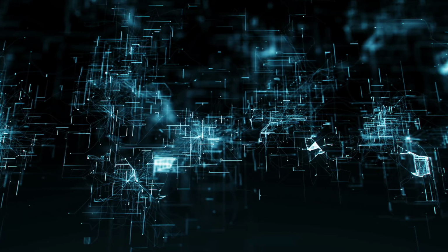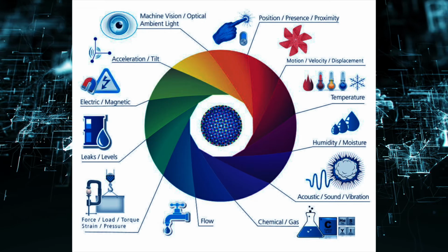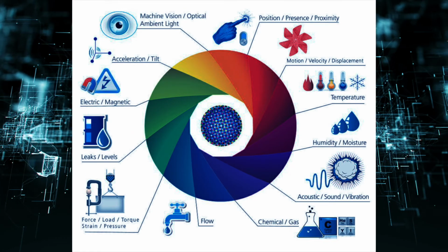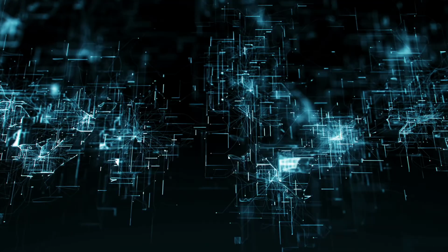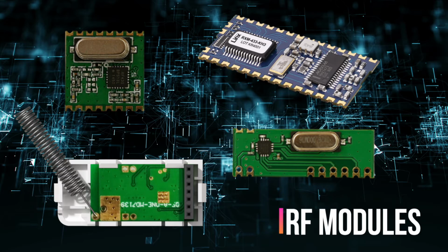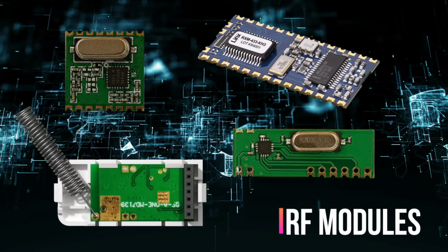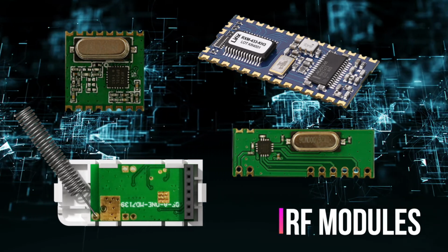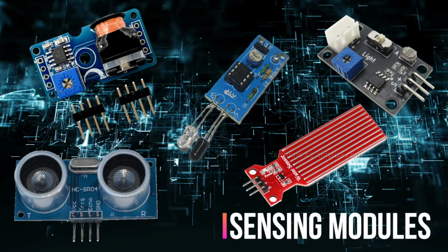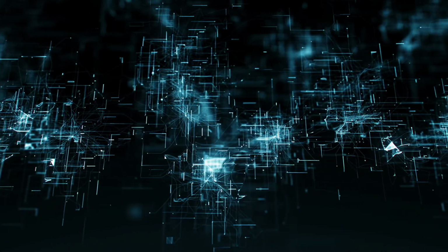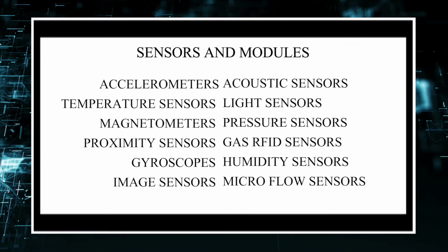The most important IoT hardware might be its sensors. These devices consist of a variety of modules such as energy modules, RF modules, power management modules, and sensing modules. RF modules manage communications through their signal processing, Wi-Fi, Zigbee, Bluetooth, radio transceiver, duplexer, and BAW. The sensing module manages sensing through assorted active and passive measurement devices. Here are some of the most commonly used sensors in IoT.